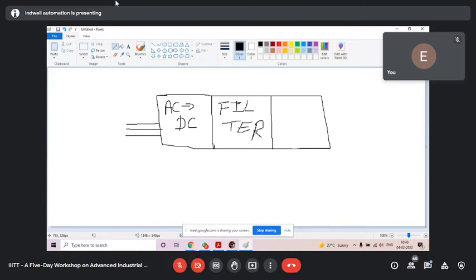They control frequency, high switching, high frequency. This means your frequency will be proportional to high frequency switching. So MOSFET, IGBT, these electronic devices will have very high frequency switching. By using high frequency switching, the things are controlled, and lastly, it will be inverted. That's why we call it an inverter also.